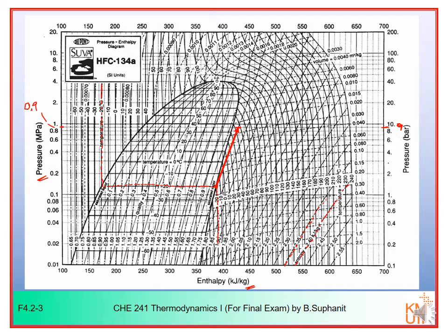Okay. Now you enter the condenser, it would be isobaric. It would be condensed to the sat liquid. Okay, so the path will move horizontally to the sat liquid line, this one. Okay, and then it will flash through a throttling valve. It will move down in a vertical direction, which is process 3-4, move down to the sat condition in the evaporator again at minus 20 degrees Celsius.